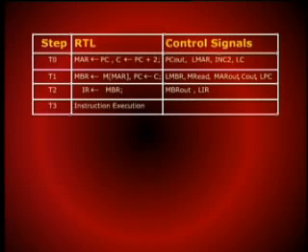So in this particular timing step, we need to have 5 control signals. For PC, we just have LPC, to enable the PC to read in from the bus; C out to enable buffer register C to feed its data onto the bus; MAR out to enable the address register to give its data at its output; and mRead for enabling the memory to be read; and LMBR to enable the buffer register to accept data which would come from the memory.